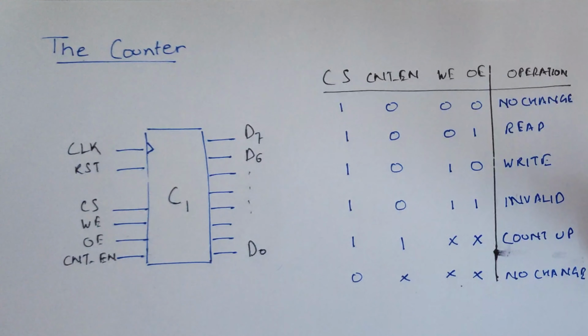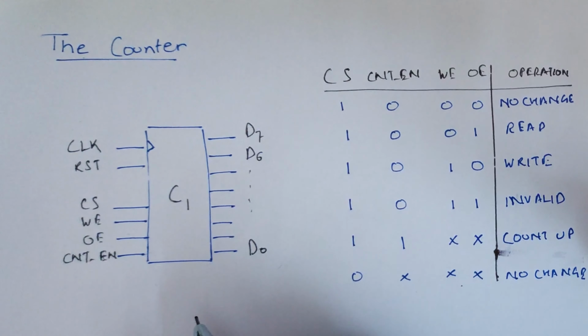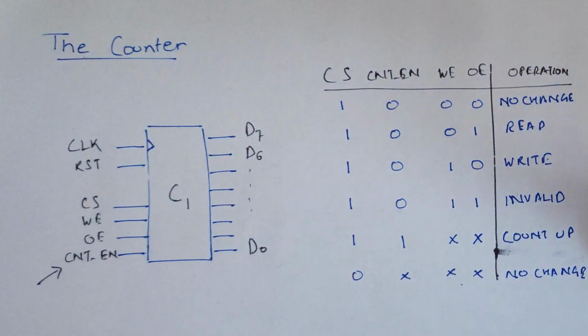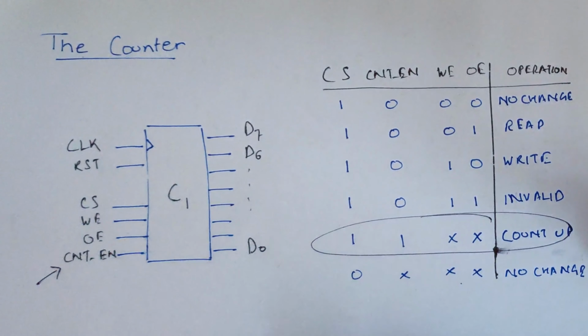A counter is a digital circuit whose value can keep incrementing on applying a certain input. The counter which we'll design today is pretty similar to the register, but it has one extra input, the count n signal. On asserting count n, the counter should keep counting up. Let's code one with behavioral modeling now.